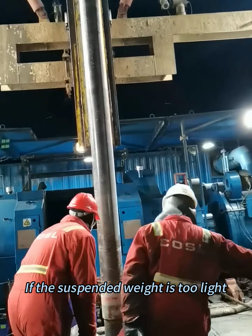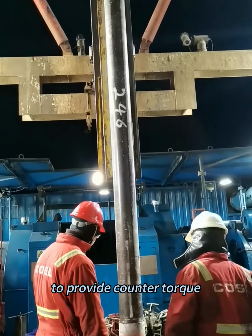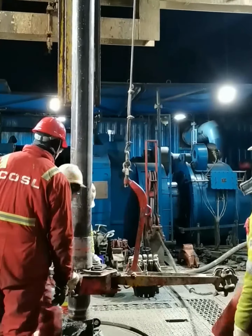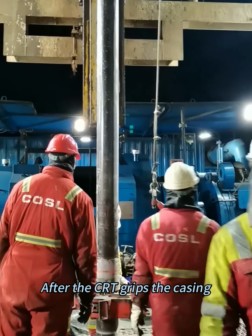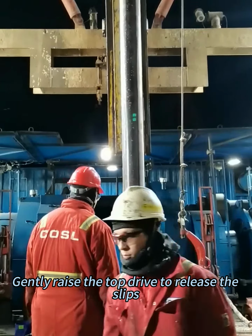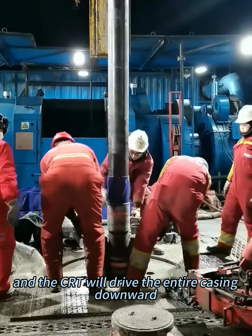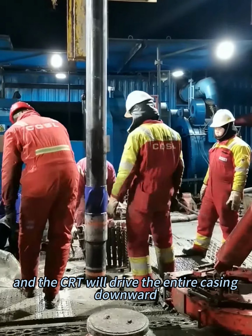If the suspended weight is too light, a backup tongue should be applied to the lower casing to provide counter torque. After the CRT grips, the casing can be lowered. Gently raise the top drive to release the slips. After removing the slips, lower the top drive, and the CRT will drive the entire casing downward.